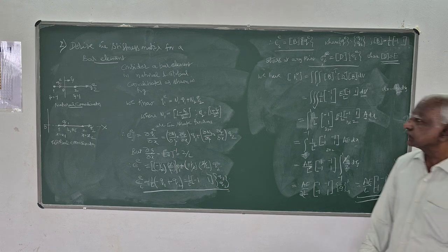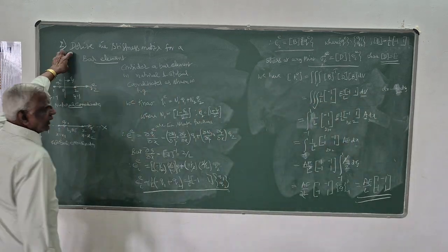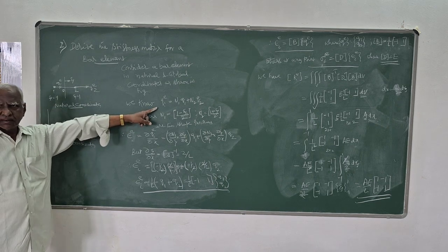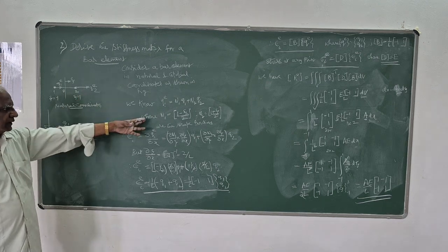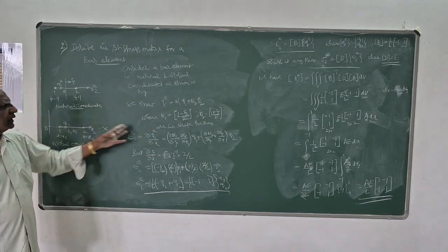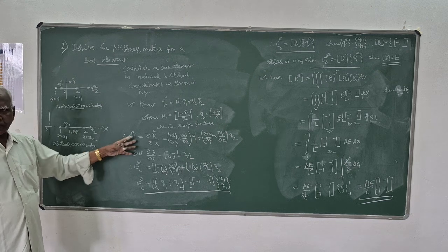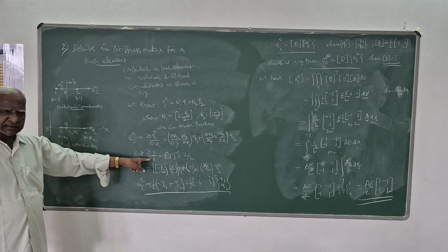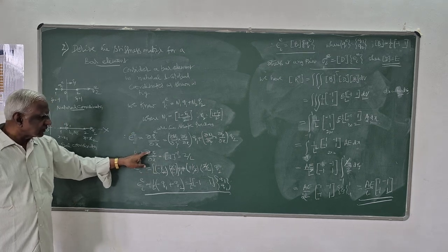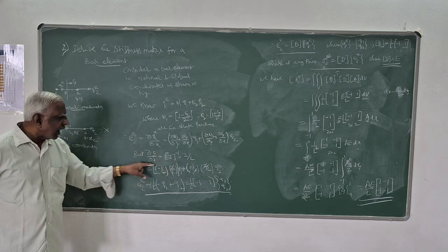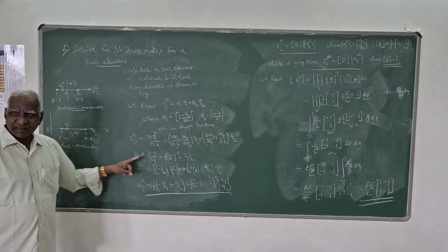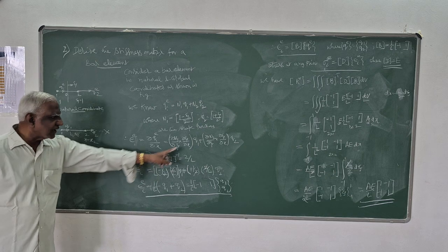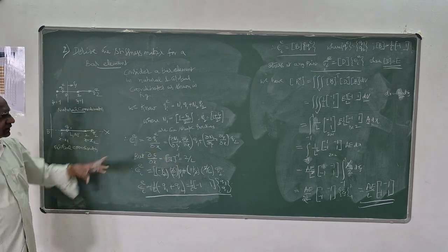You see that, this is the stiffness matrix of a bar element. First you have to write the displacement at any point in terms of shape functions in natural coordinates. Then you have to write the expression for epsilon, which is nothing but the derivative of this displacement. Then you have to use the Jacobian relationship I already have here: dpsi by dx is 2 by L, or dx by d psi is L by 2. Therefore dx is equal to L by 2 d psi.